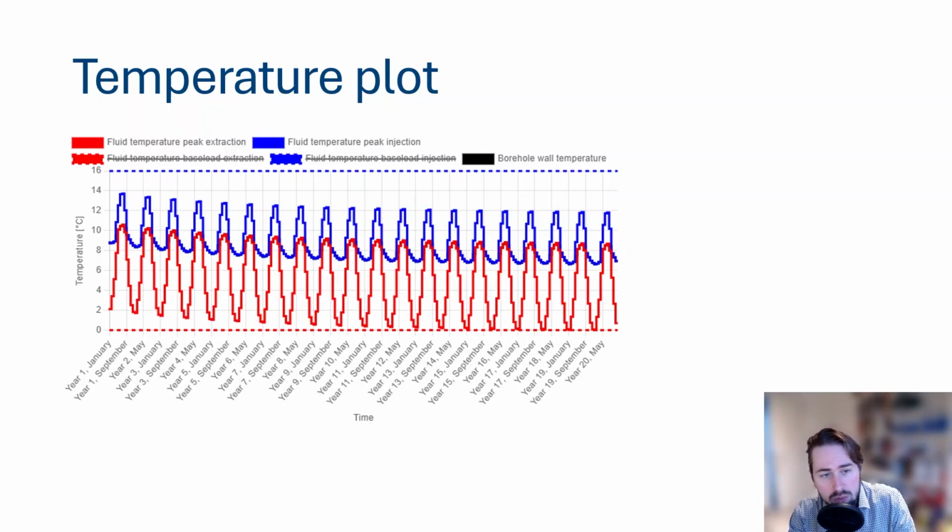We can also see a figure like this, where we again have a negative imbalance and we are now limited by the minimum average fluid temperature. This is typically the profile of a residential building where there is a lot of heating demand and especially sanitary hot water or domestic hot water demand. So we're limited by the minimum average fluid temperature. And perhaps you can already see me coming.